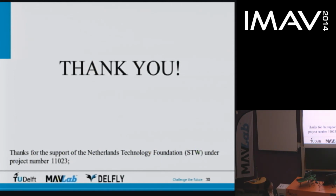The question is, in the kriging, interpolation is used to reconstruct the wake, but why just use different planes? And to my knowledge that algorithm is very dissipative, which means you're going to lose all the small scales. Yeah, for sure. By kriging, we definitely will get rid of some small structures, and there is also a smoothing function inside the kriging.